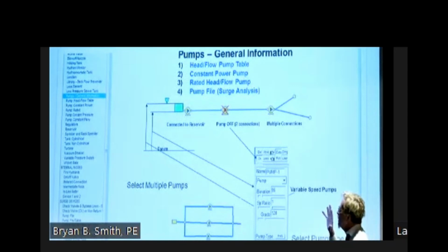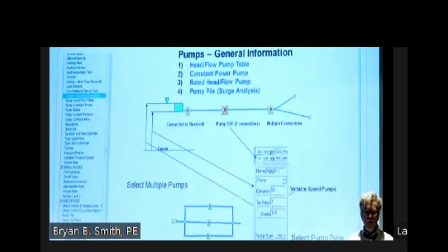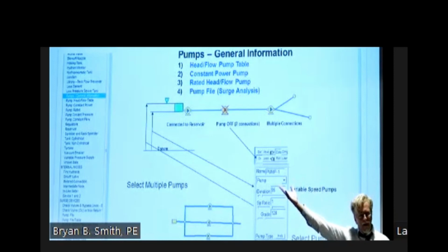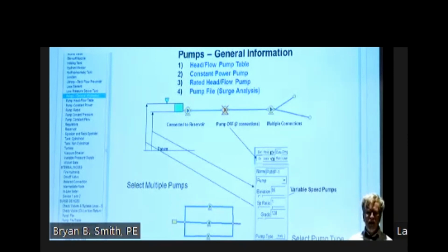This is, again, just a screenshot from the software, with everything about your piping system, the check valve, the pump. So many systems don't have the pump curve. I ask, what's going on here? They say, I've got pressure, I've got flow. I'm like, okay, I can work with that. It's not perfect, but we can input that in the model.